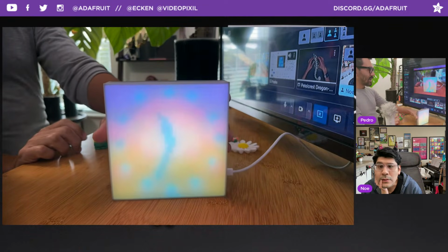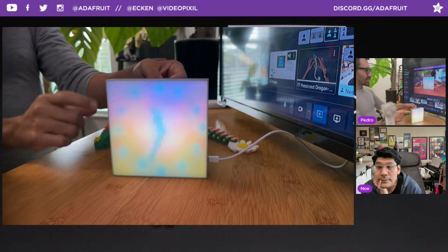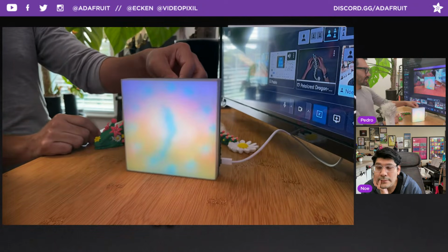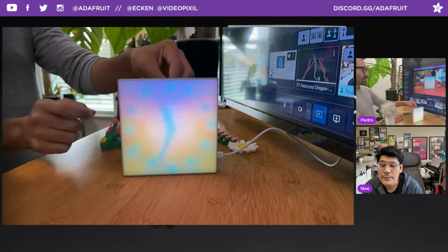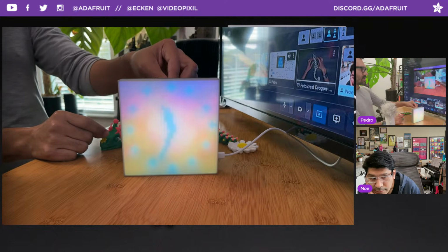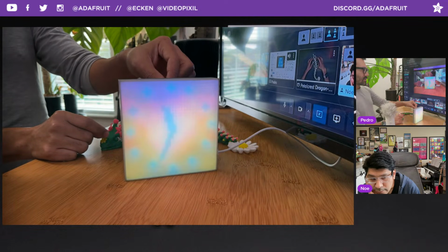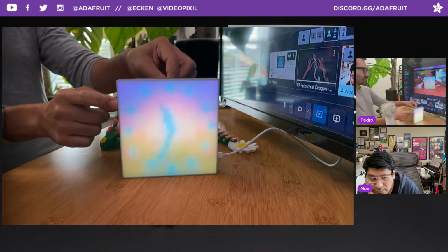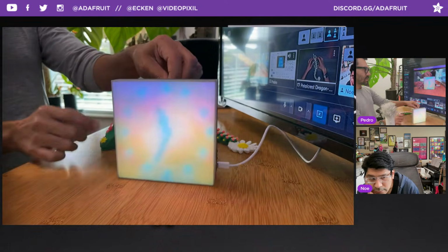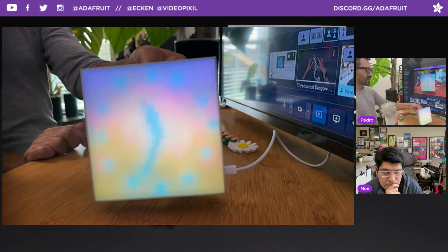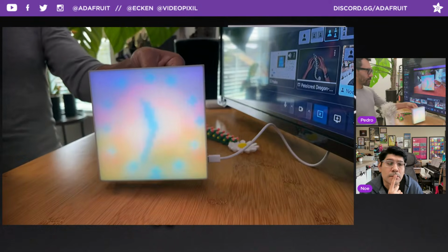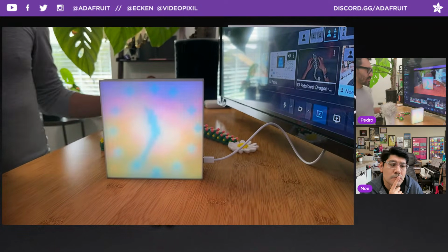It's the PWM. We were talking about last week the distance and then the thickness of the diffusion. Yeah. Okay. I wound up staying with the 0.8 millimeter thick. That's 4 layers. Yes, I tried 1 millimeter and that was too much. It was not diffusing as much, and I struck a balance in terms of how far it is away between having it blurry and where you can see the individual pixels to make out where the 5-minute markers are. So just a compromise between those.